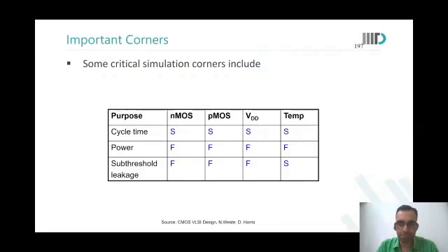Right, and obviously it will consume more power in the fast corner. Yeah, power would also be higher because of leakage being higher. When your voltage of operation is higher, it is CV squared F. The capacitance is higher when the devices are fast, V is higher, and we know frequency is highest when the temperature is low. So CV squared F, or power, is highest when everything is towards the fast side. Okay? Yes, sir.